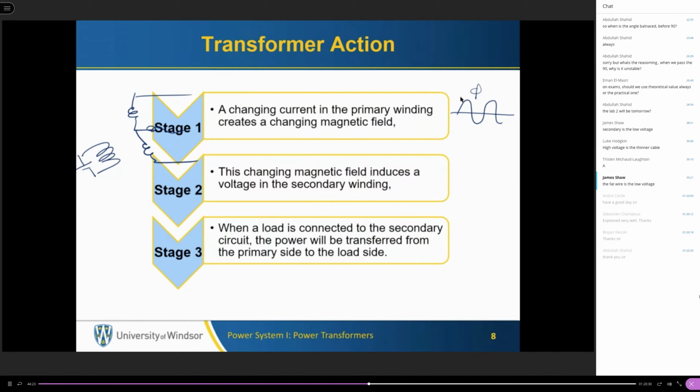That is why we have to rotate the rotor, because the field generated by this DC source is constant. If everything is stationary, the field of the rotor is constant. So we have to rotate the rotor in order to have an alternating magnetic field applied on the stator windings. And in transformers, we don't have any rotation. So for transformers to operate, we should apply AC current.